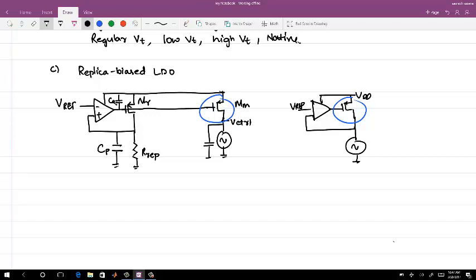Now, in the case of the regulator on the right side, you have a smaller resistance. Let me call this the effective RVCO. This was a small resistance, and in order to make this pole a dominant pole, I have to put a larger cap to make it dominant. Now here, if I'm using this replica, this is something like n times larger, right?